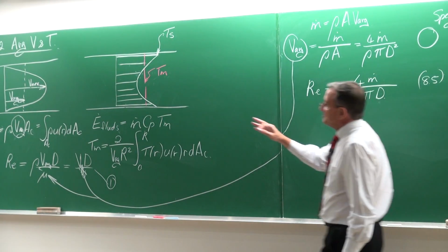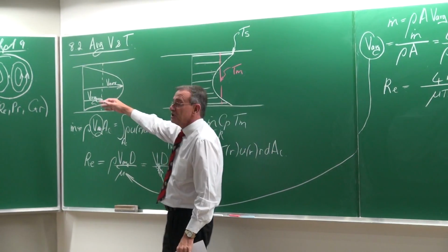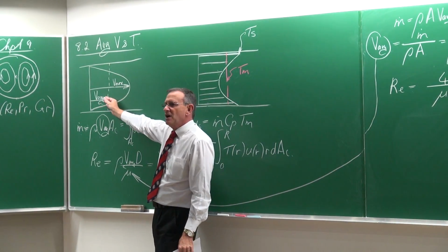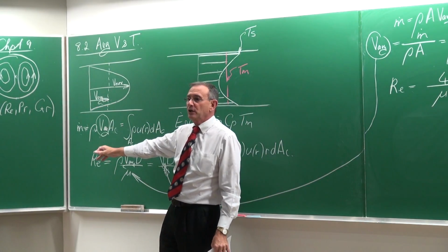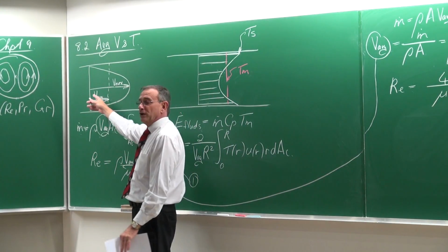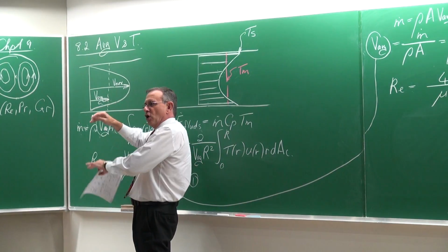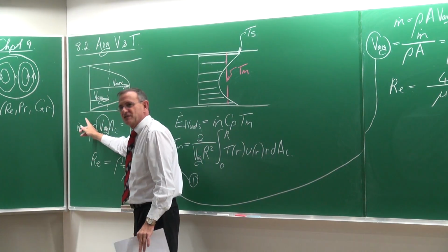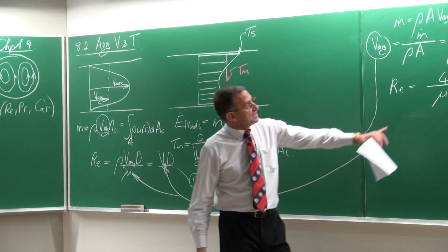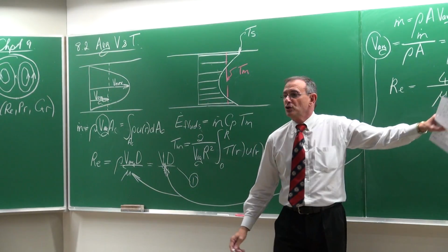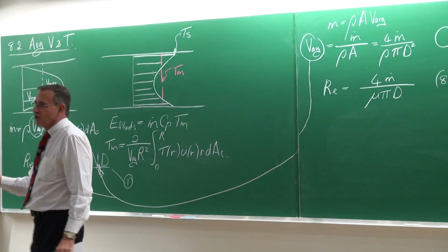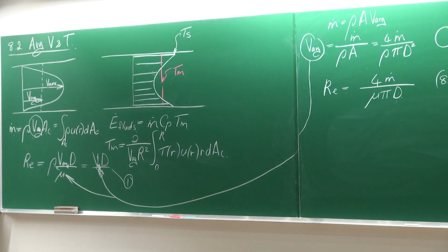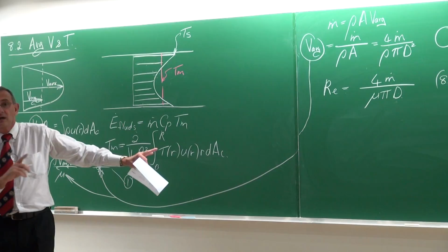Coming back to what I've said, with internal convection problems it will be very seldom that somebody is going to tell you the velocity going through the geometry. Normally it will be the mass flow rate. If you've got the mass flow rate, you can very quickly determine the Reynolds number. Otherwise, you must always calculate the velocity first. So it just saves you time.